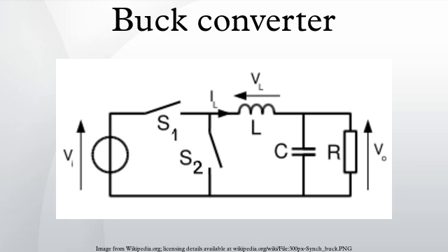Effects of non-ideality on the efficiency. A simplified analysis of the buck converter, as described above, does not account for non-idealities of the circuit components, nor does it account for the required control circuitry. Power losses due to the control circuitry are usually insignificant when compared with the losses in the power devices. The non-idealities of the power devices account for the bulk of the power losses in the converter.